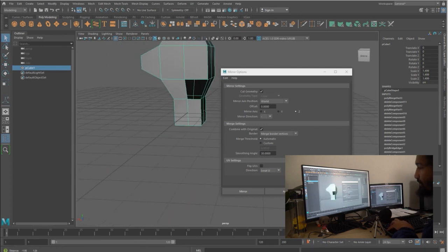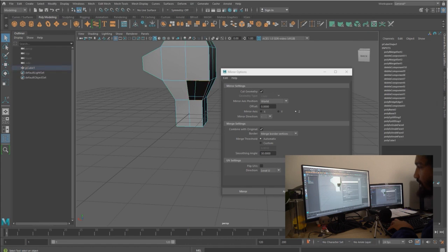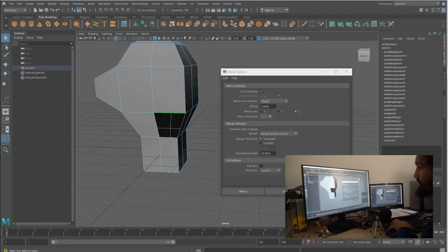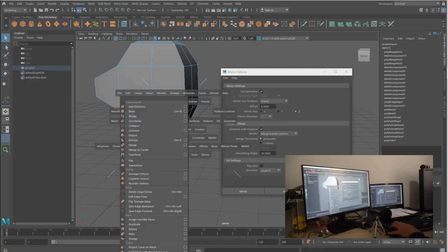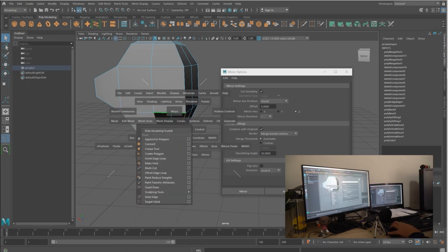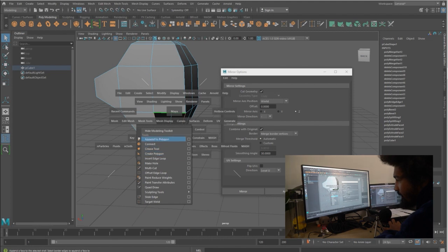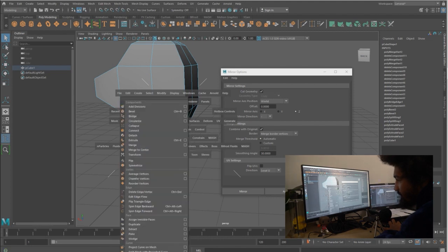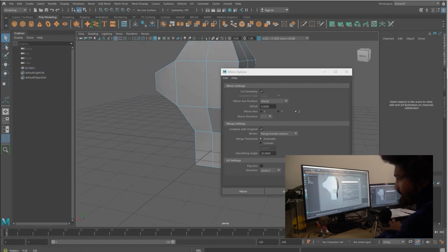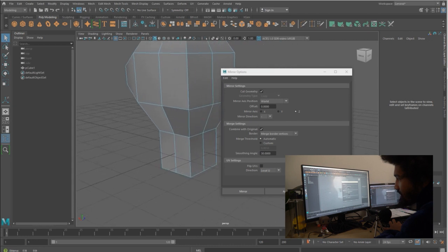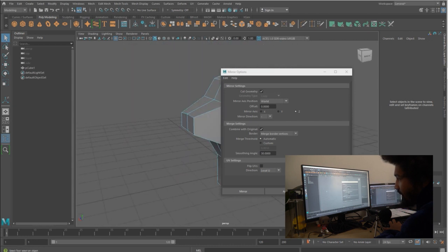Here I have a hole, so I want to fill the hole, so we double click on the edge, and we see it's taking all the edges, so it's a proper edge loop. Edit mesh, mesh tool, and no, the fill hole is not here, not here either, it's here, fill hole, remesh. You see it's gonna create a face based on the edges we have.